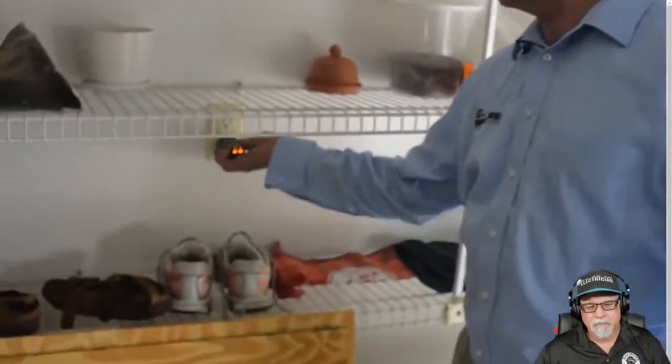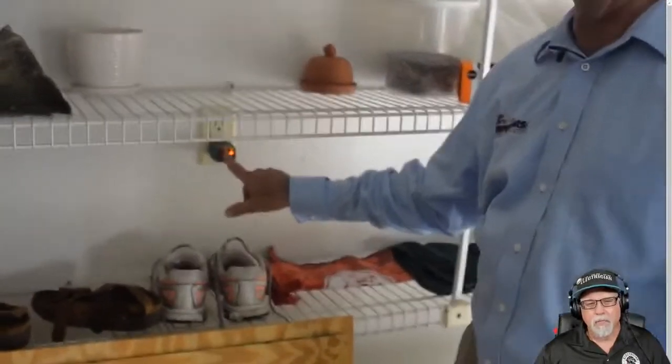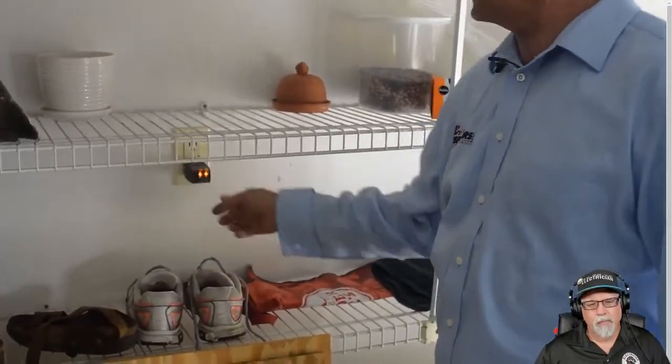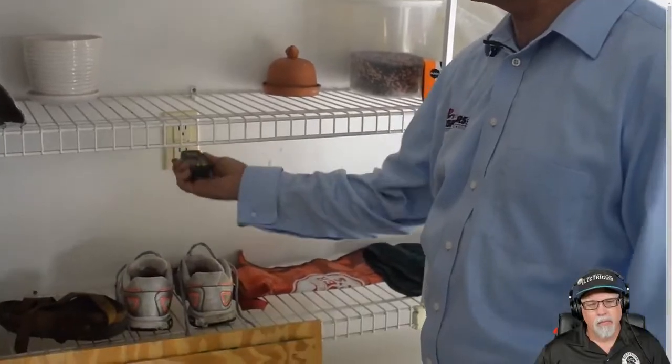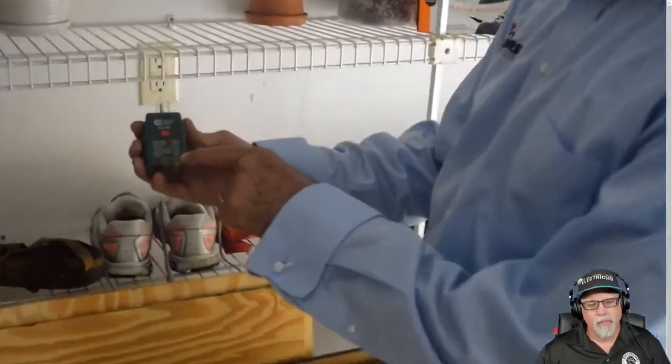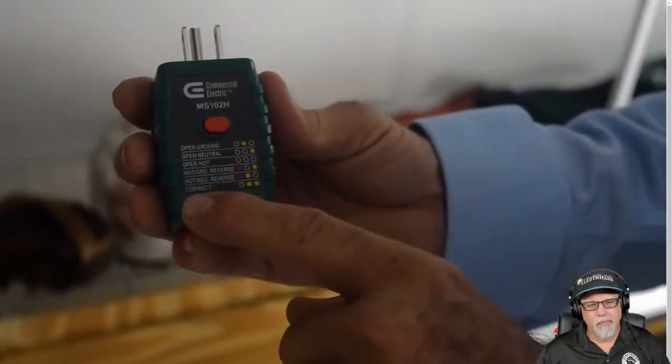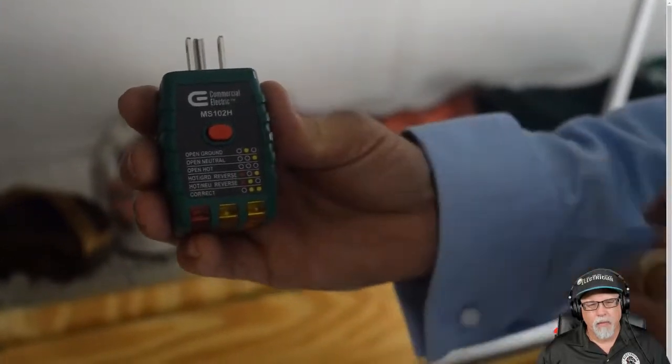The reason being is that it's to protect any individual so they don't get shocked if the outlet malfunctions. The way to test that is you simply plug it in there and it lights up. In this case, it's telling me that it's properly wired. So you can check this on any outlet to see that it's properly wired. If it's not properly wired, it has a nice little code here which tells you what the little lights mean. So you can see that 2 yellow dots means that it's correct, and then any variation other than that. So it's a great little device to do your own check for you.